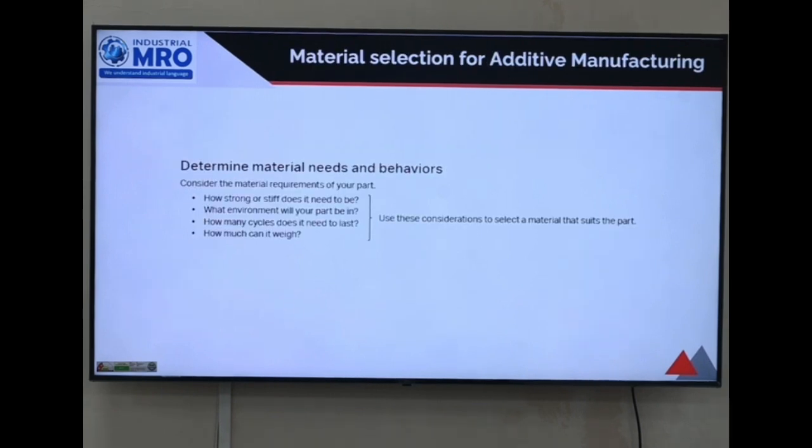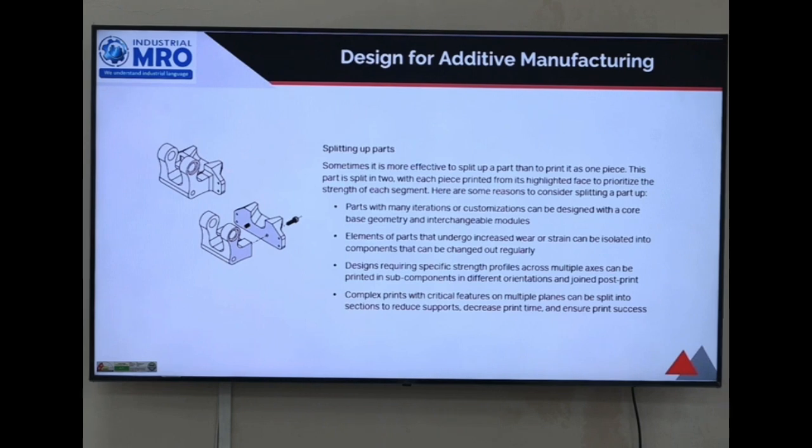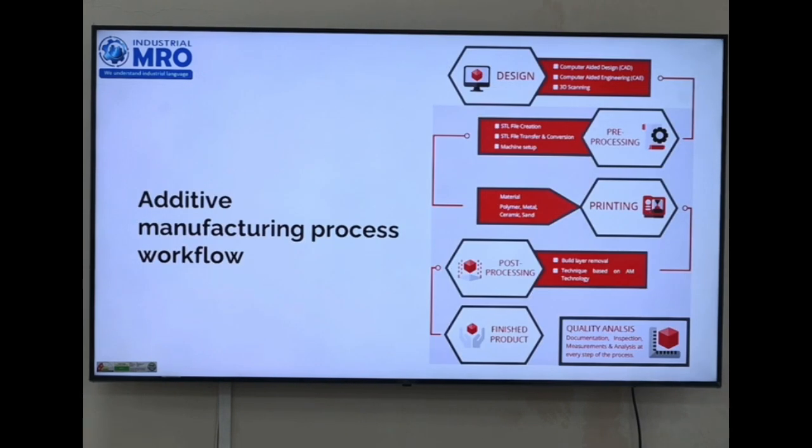So the next step, if we go back to the workflow, is printing. Before printing, I need to select the material. Definitely, material will be defined in computer-aided engineering. By this material setting, I mean the temperature settings of the nozzle, which you have to do in the slicer.